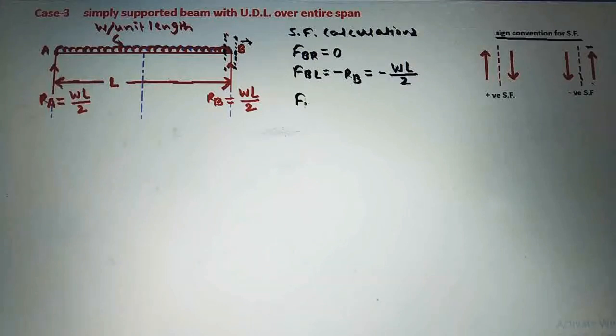Next we will take point A here or support A. So we will write shear force at a section just right of A. See here, just right of A. This is point A. Just right of A is this section. Now see on the right side, first is load RB, and that is acting in upward direction. So right side of a section, load RB is acting in upward direction, so it will be negative. So it will be minus RB.